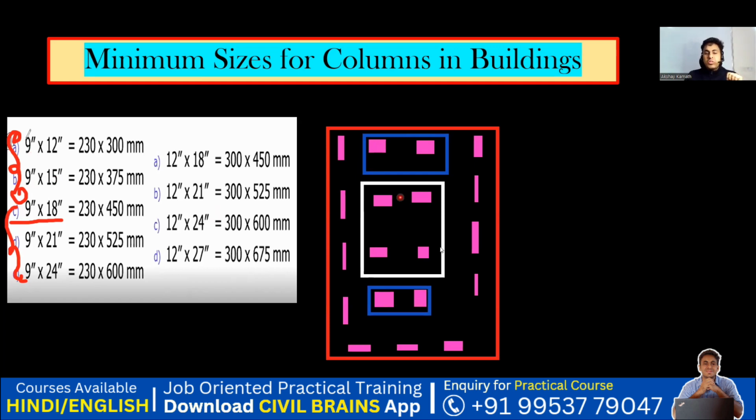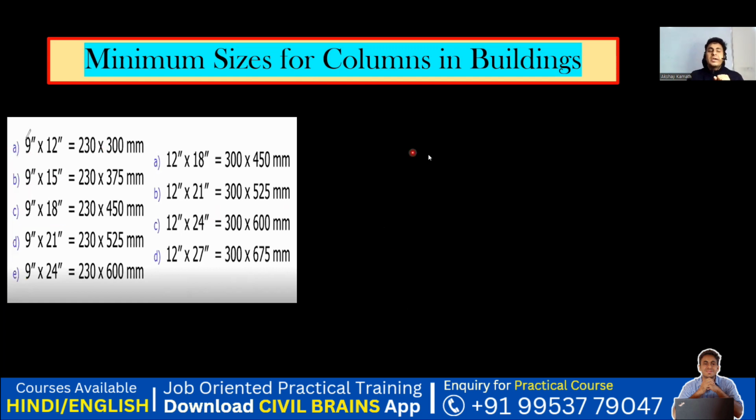Why? Compared to these four columns, the load coming on these two columns is less, right? Here from all four sides the load will come. Here also it will come, but let us say the load coming is comparatively less. Again, it depends on the distance between the two columns, the length of your slab and all. So I'll provide a 9 inch by 15 inch column for this. Pretty simple.